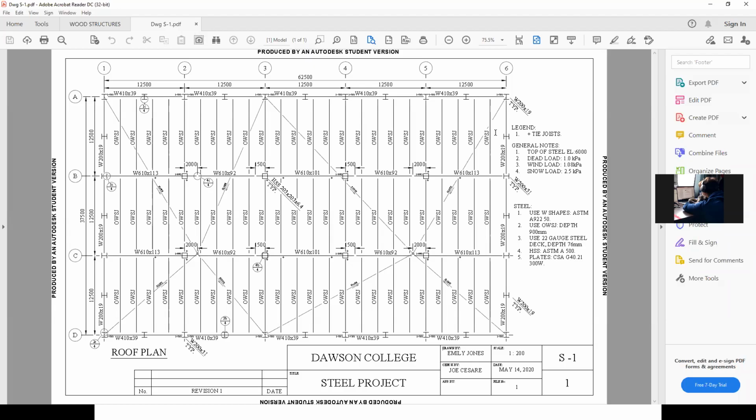Now, the architect can either use sloped insulation to create the slopes, or he can ask you to create the slopes. So you'd have to discuss it with the architect how big of a basin he wants to create, in other words, where does he want to slope to? Between you and the architect, you'll decide that we'll put a roof drain here, and a roof drain there, and then the mechanical engineer will calculate, based on the size of the roof, the size of the drain and the pipe. So the mechanical engineer gets involved afterwards.